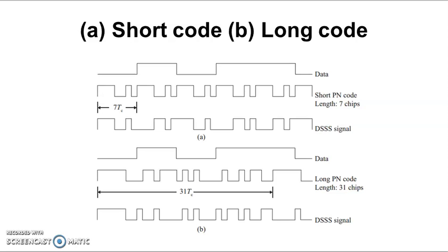And the spreading waveform is periodic with a short code. We can see that here we have the short PN code, which gives the spreading waveform. The spectrum of the short code modulated signal is periodic, with lines occurring at 1 by Tc here.